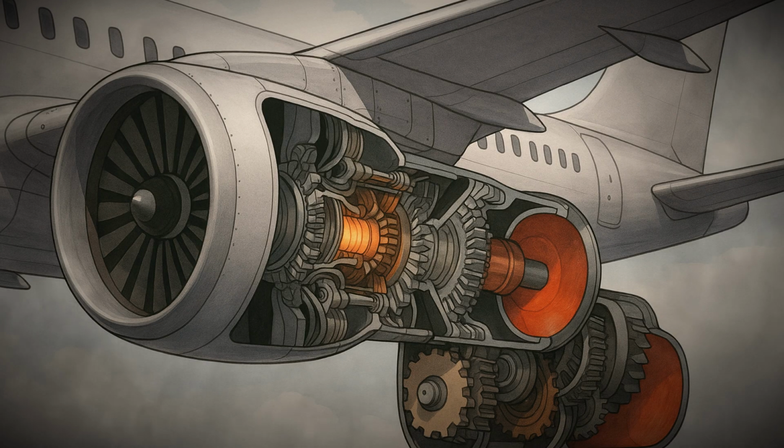If the angle of attack becomes too steep, the airflow over the top of the wing can no longer remain smooth and attached to the surface. This results in a turbulent wake behind the wing, known as flow separation, which causes a rapid loss of lift. This phenomenon is called a stall, and it is one of the most important considerations in the design and operation of aircraft. Pilots must be trained to recognize and recover from stalls, and engineers must design wings and control systems to minimize the risk of stalling during normal operations.